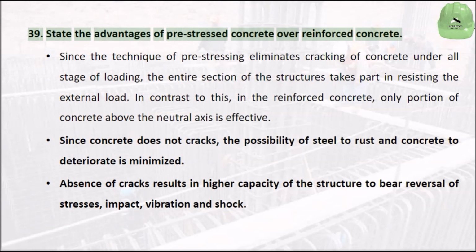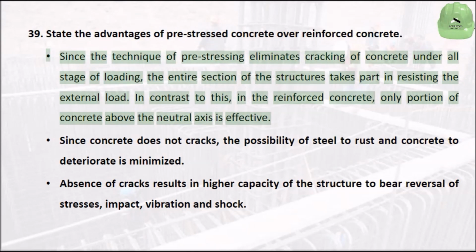State the advantages of pre-stressed concrete over reinforced concrete. Since the technique of pre-stressing eliminates cracking of concrete under all stages of loading, the entire section of the structure takes part in resisting the external load.